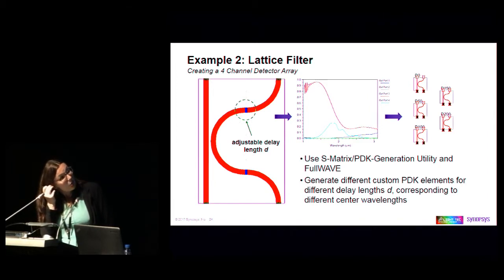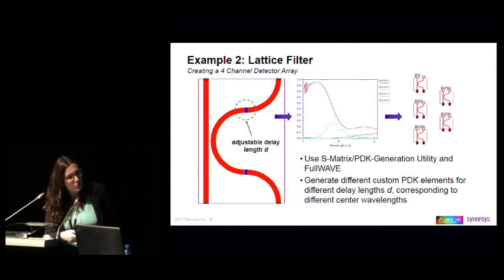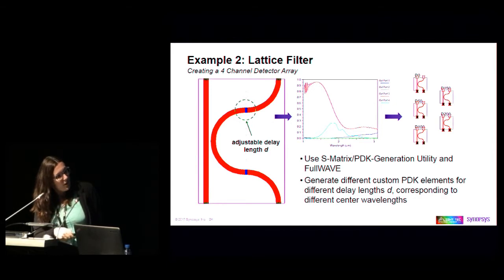Inside the component tools, at the component level, we can study again the transfer matrix for the coupler, for the different ports, and generate the S matrix of the coupler for different distances. For this type of design, FDTD, so full wave in RSoft, will be the right software to use.